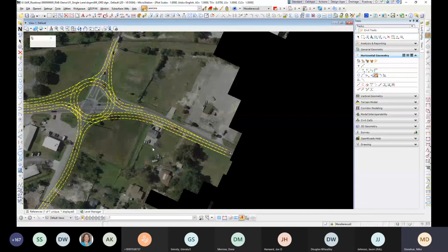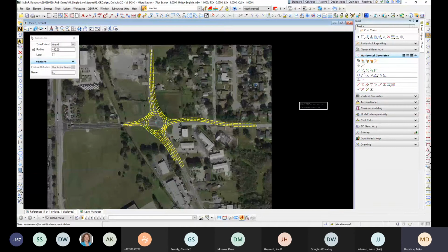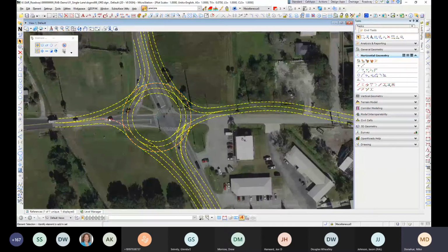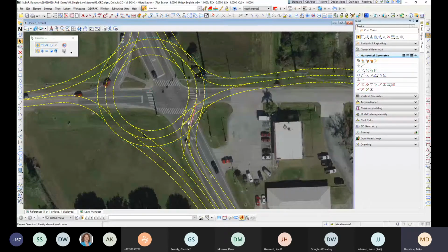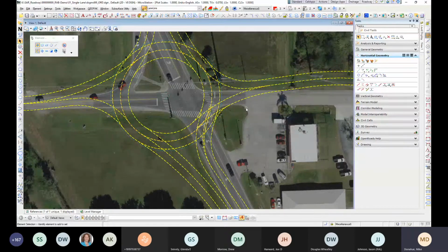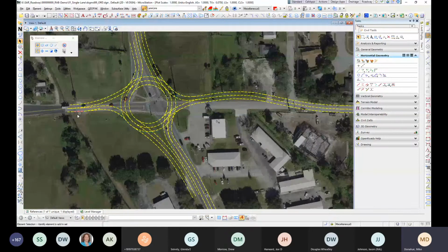So it is 12:38, and I would like to show now just how to clean this up and get rid of some of this intelligence, right? So you have a roundabout laid out, you have all the intelligence built into the line work. So if your fastest path is not giving you the results that you want at any given entry point or exit point for that matter, or your path overlap is not working out for you, you can do all that in this file or come back into this file and make a change, whether it's dynamically changing the overall size of the roundabout or some of the entry links or angles. If your speed's pretty slow here, you may want to flatten this out a little bit and check it again and see if it's still within tolerance. But doing it this way is going to save you from a lot of deleting and redrawing of elements as you go through performance vetting.